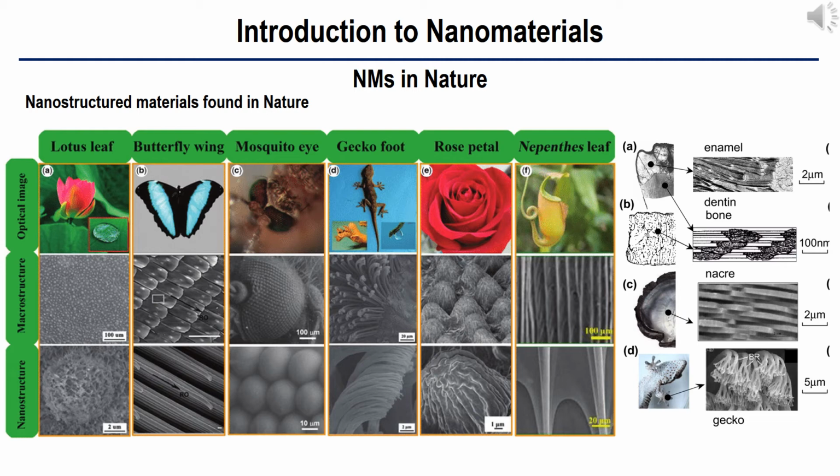Second, the leaf looks like a nanoengineered surface. For example, as shown in the second and third rows in this figure, you can find some hierarchical structures of the leaf, which make the leaf have large surface areas and protruded parts. These structures work as a Cassie-Baxter structure, which increases the surface energy of the structured leaf.